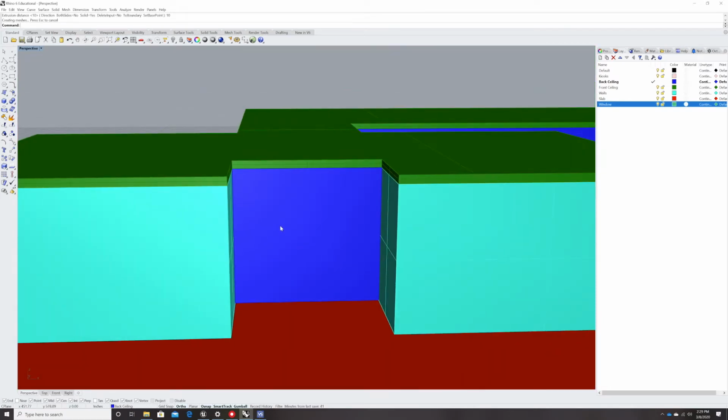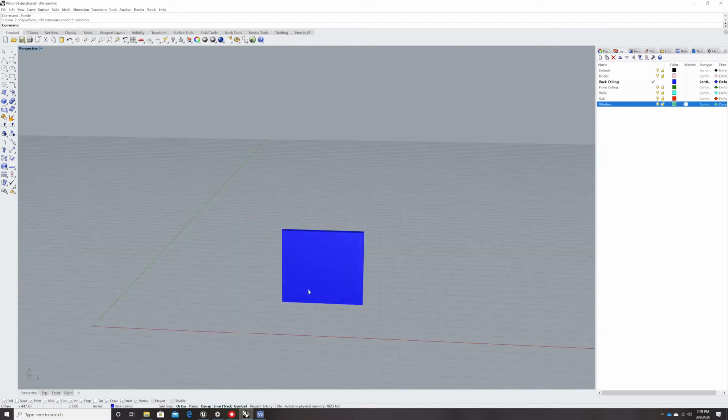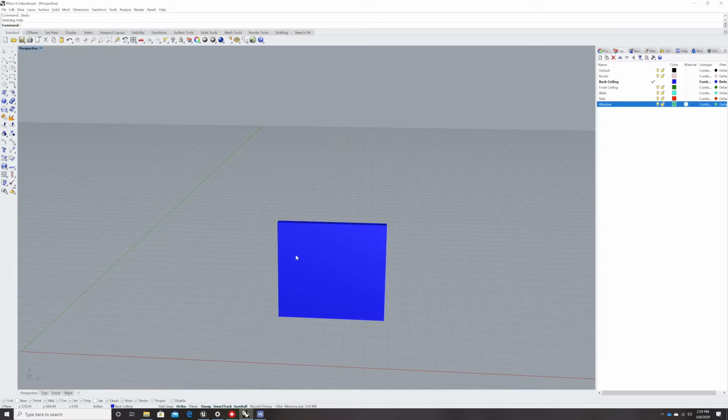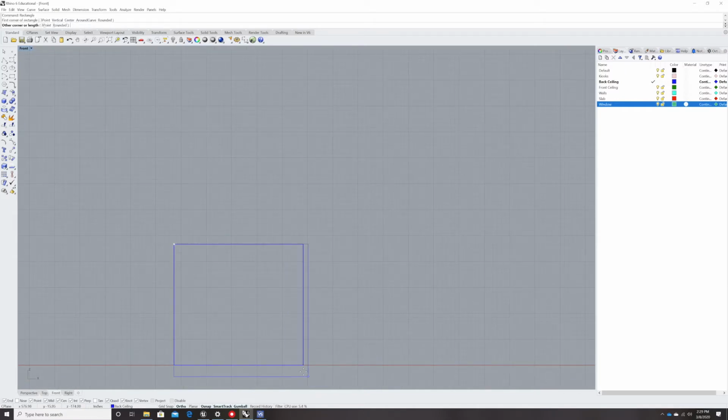Okay, so now if I click on this and isolate it, and then I'm going to hide this. Oops, undo. I'll just draw another rectangle from a front view to there. Click on it, grab the extrusion, hide it. Okay, so now we've got a curve that perfectly outlines our shape.